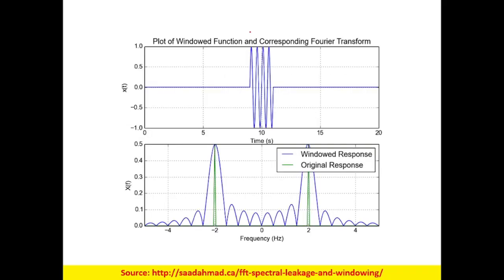If we are having a frequency component like this, then if you look into the frequency response, it should be quite sharp. But when we are applying any window, window means, we talked that for DFT we have to truncate the signal. Truncate means we are applying a window and we are taking the signal from a specific part of the time. So in other time instances it becomes zero.